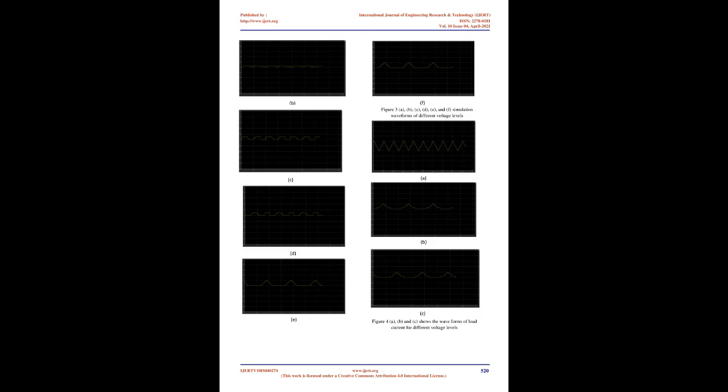With the proposed snubber, synchronous rectification operation is compared to that of diode boost, with a particular attention to the contribution of nonlinear MOSFET parasitics. Barth et al. have proposed a model [14], experimental evaluation of capacitors for power buffering in single-phase power converters.